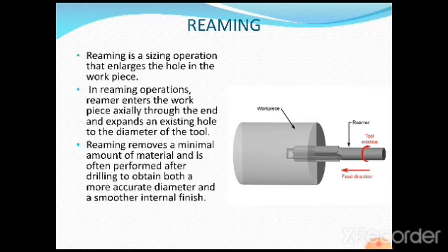Actually, it is going to enlarge means what? In reality it is going to remove very little material to give a fine finish on its internal surface. In a reaming operation, the reamer enters the workpiece axially through the end and expands an existing hole to the diameter of the tool. Of course it expands, it provides slight expansion, not a major expansion of the previously drilled hole.